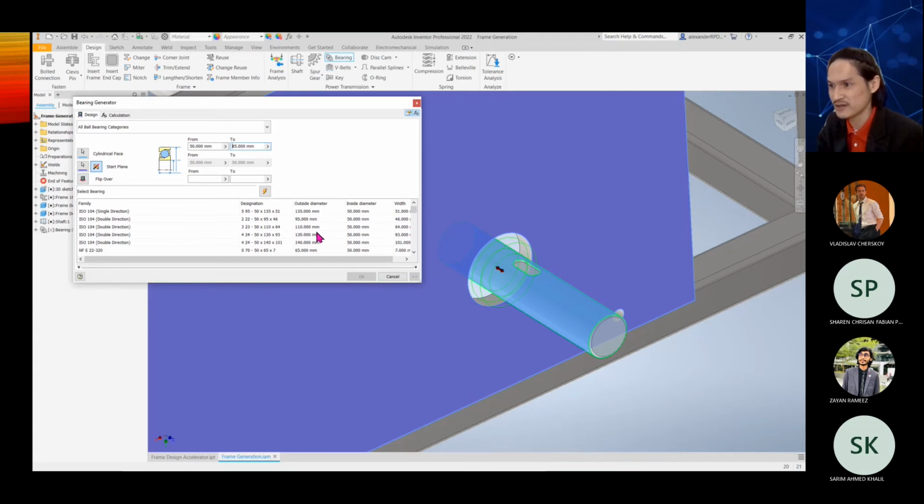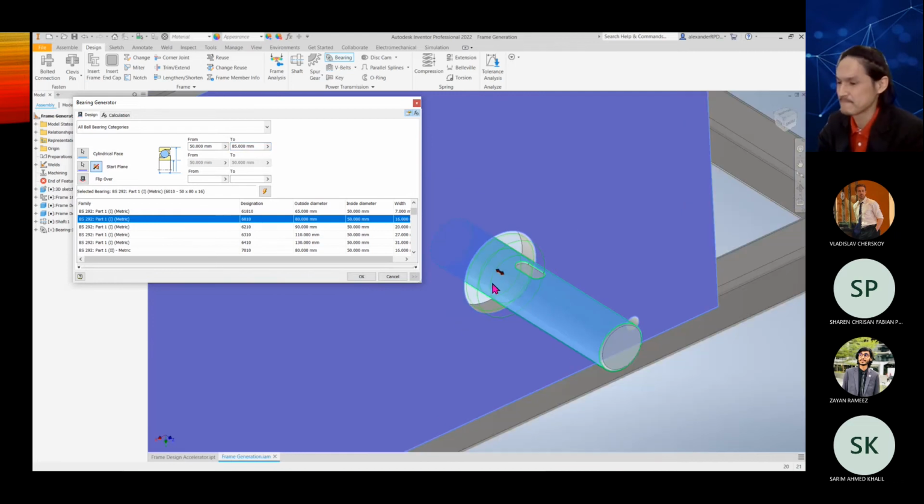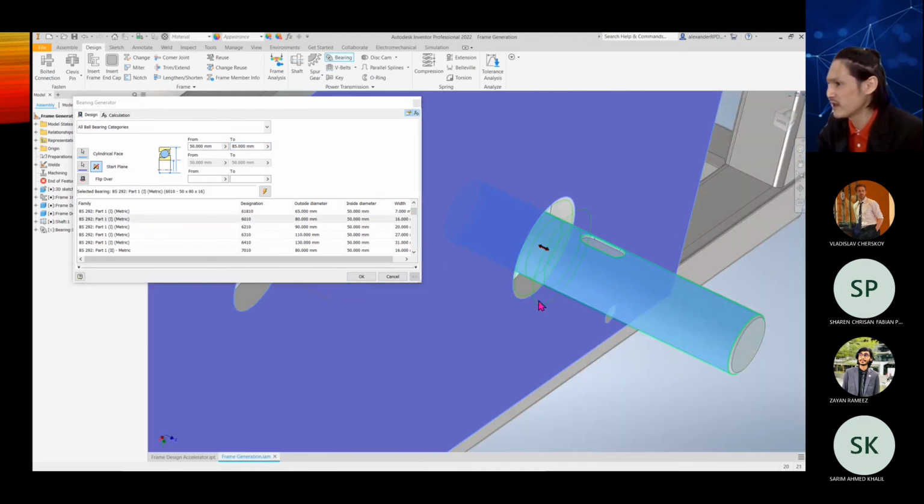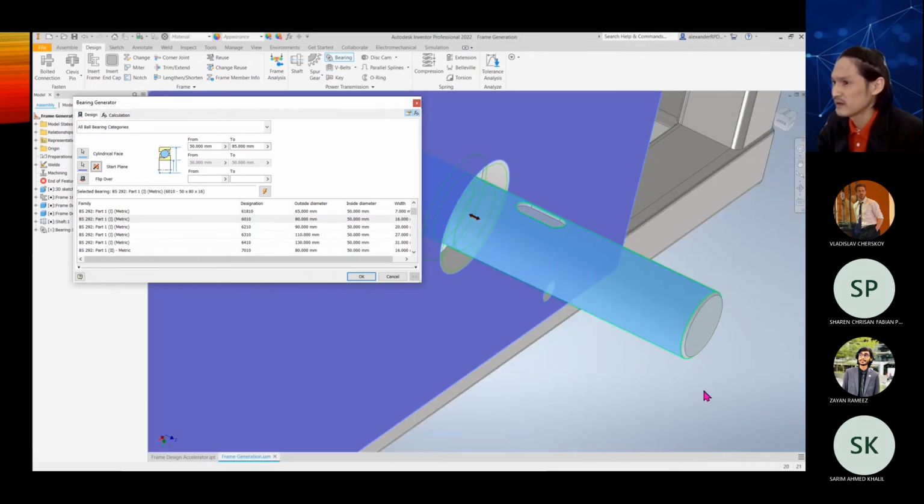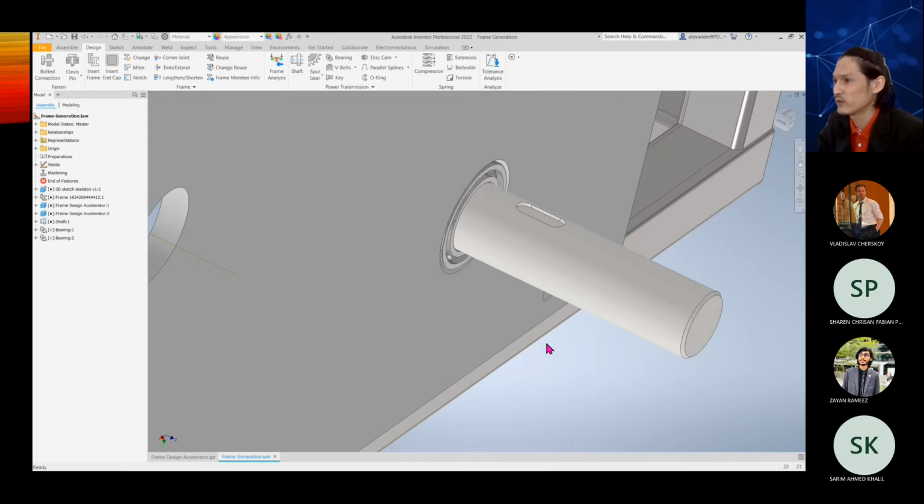ISO, I know there's a 78, but let's say I just want to select 80. Maybe I select this. Okay, 80. Now be careful on the preview. If you see that they are outside, you need to flip them to insert them. Okay, flip them, insert them. The list they give to us definitely can fit the shaft. The shaft I just adjusted is 50, so that's why it's 50. So now I click. So I have one over.